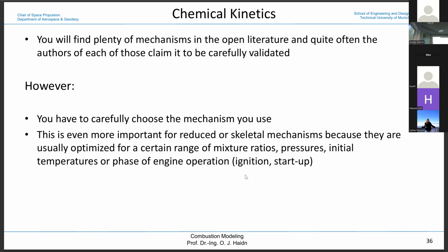So in order to be able to do that, what they do is try to find out the local Damköhler number in that computational cell. And that means they have the reduced chemical mechanism. They try to identify the characteristic time out of 50 reactions. So they select those which they feel, based on the sensitivity analysis, are the most important reactions. Out of that, they predict a time scale, and then they relate it to the local fluid time scale in the system.